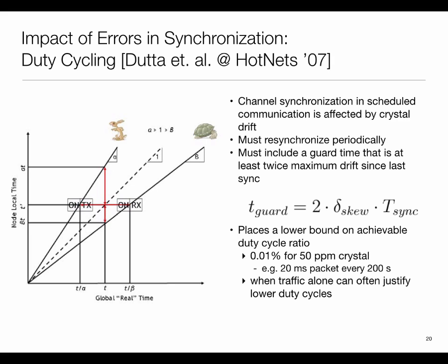The better the clocks you have, the more you can sleep. But the flip side is we saw that better clocks consume more energy, and therefore I may actually end up losing, because while sleeping you still need to maintain time. And if while sleeping you need to maintain time at a level which requires milliwatts of power, then you will end up losing out.